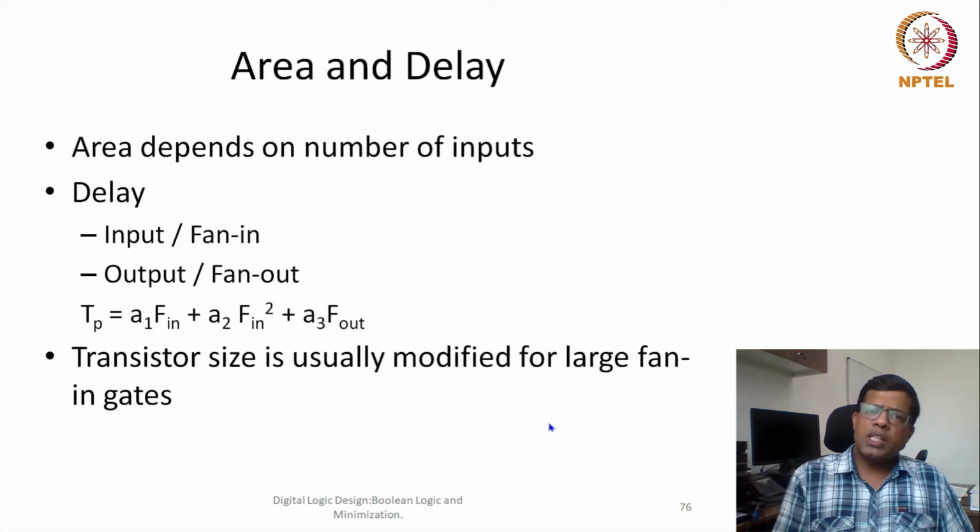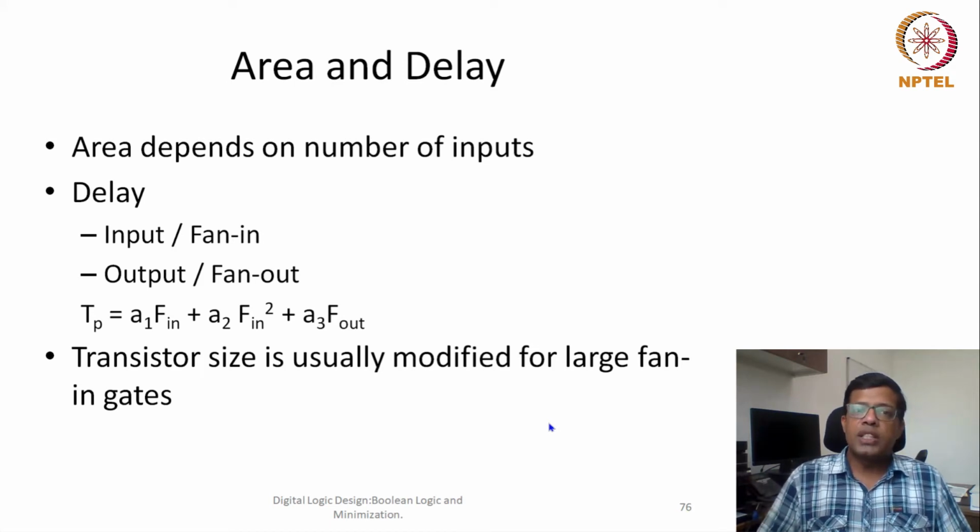Also there are some other factors which would help in calculating area and delay, like technology or how designers are designing. So this information is sufficient for now: the delay would increase more than linearly, or squarely proportional, to fan-in, and as the fan-out increases, the delay would also increase.